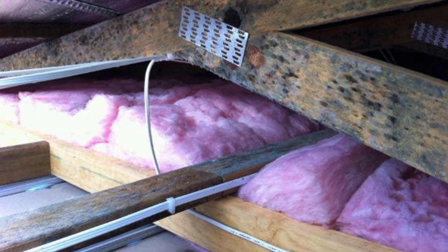We can also get mold wherever we have moisture and we've got a food source, and we've got plenty of food sources within our building constructions with timber, cellulose. We get mold growth. A lot of people might not think it's too much of an issue up in the roof, but if air can get into the roof, and clearly it can because that's part of the problem here, that means that air can also get out, and with that can come mold spores. When those spores get into the living space below, that's when we end up with very unhealthy conditions inside the house. So they're just some of the issues that we have.